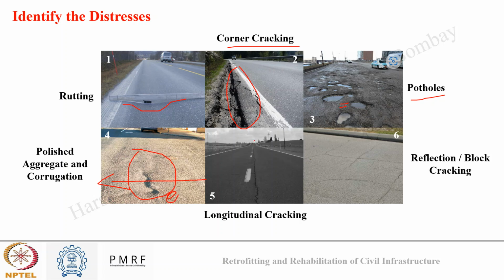Okay. These are longitudinal cracking. Okay. And these are reflection or block cracking. Okay. So, just knowing the cause of distress is not enough. You also should know what type of distress it is so that we can choose an adequate repair for it.